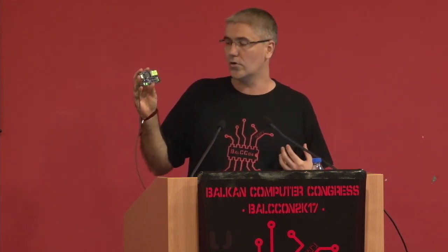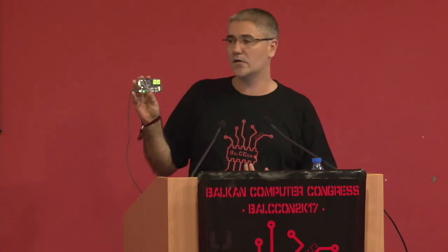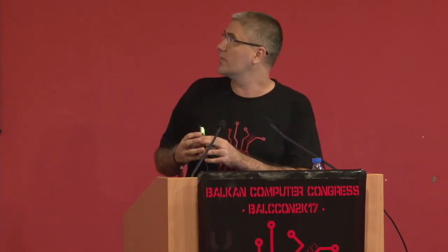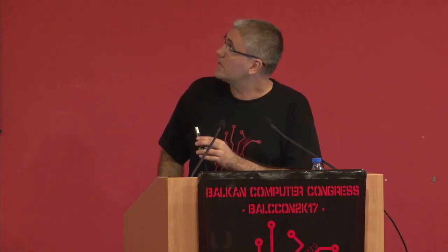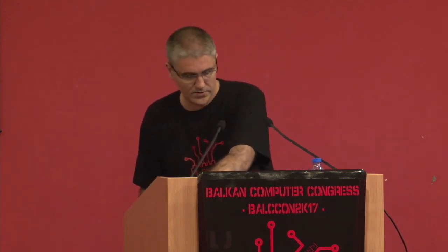So basically, the FPGA is always empty. There is basically nothing, never. And when you start it up, you need to provide a way to put the bit stream inside. It's automatically done here by using this EEPROM, a flash of 1 megabit size. I will just need to zoom in a bit.